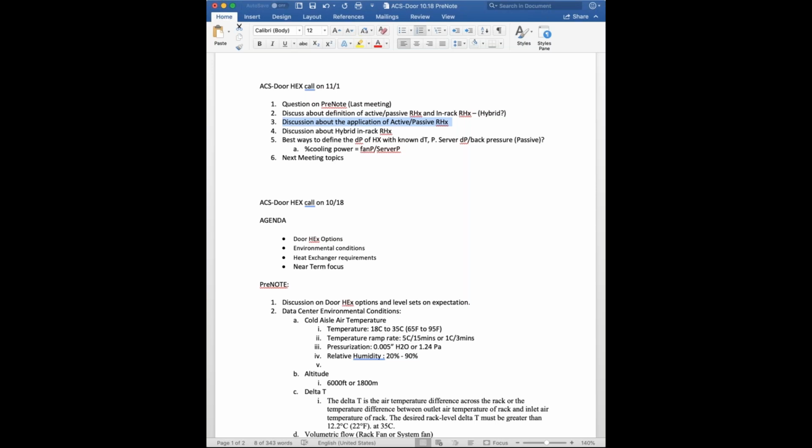Now, what you can do there though is go to a different coil design, which is a lighter duty design, depending upon the total heat load. It depends on compaction and how much IT heat load you're dealing with in general. But there's some fine tuning, obviously, that can be done with the coil selection on the rear door heat exchanger for a much lower pressure drop, based on the fact that about 70% of the heat's being removed through the liquid cooling loop.